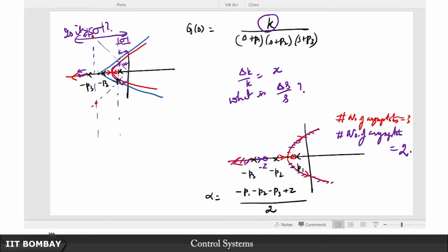But more importantly, what happens is now the directions of the asymptotes are along 90 degrees and along 270 degrees. So now, provided that this alpha belongs to the left half plane, right? Because we haven't shifted this 0 much to the left. If you shift the 0 far to the left, then this positivity far outweighs all these three negatives, no?